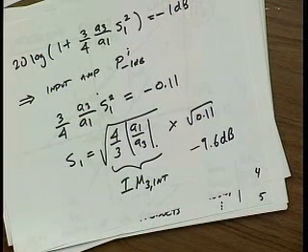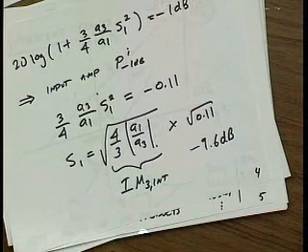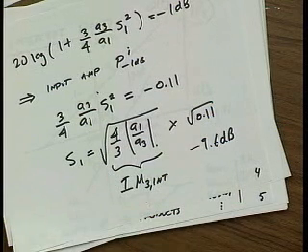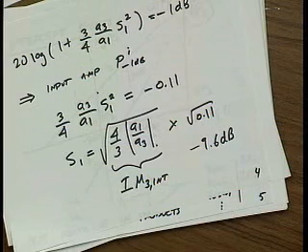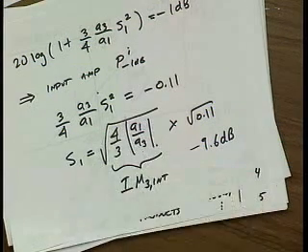So if someone tells you, I have an amplifier, it has a plus 0 dBm intercept point, okay? And I want to operate it at the point where the gain is dropped by 1 dB. Then you know you back off 10 dB from that intercept point, and at that point the gain is dropped by 1 dB. Okay? So keep this number in mind because it's going to pop up over and over again in today's lecture.